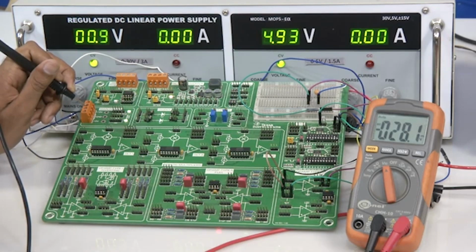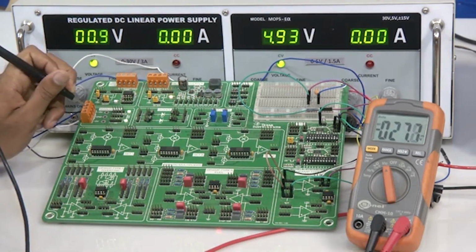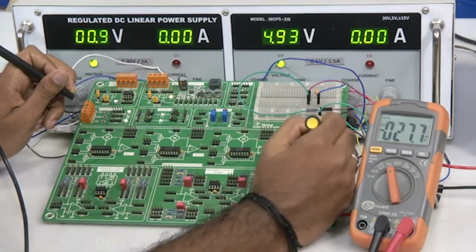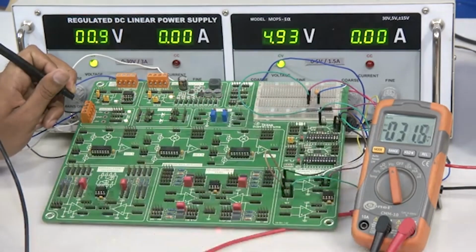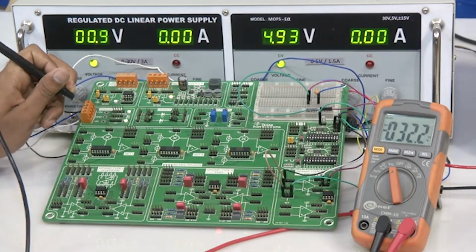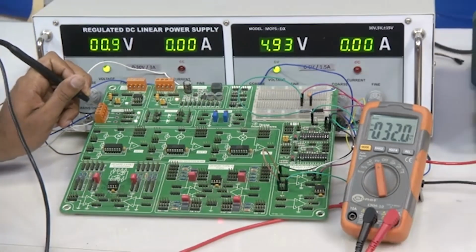Now, we have made the D1 bit high and brought the D0 bit to 0. Keeping the multimeter connected, let me just change the first 0 bit also. Now, 2 bits will go high. Accordingly you see a change in voltage, it has become 31.9, roughly 32 millivolt. What was the previous voltage? It was 26.4. Now, we added a 2 bit change, so we got a change from around 26.4 to 32, correct.